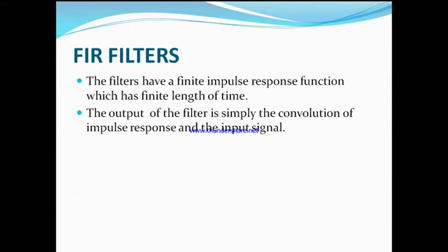Before that, we should know what is meant by FIR filters. These filters have a finite impulse response function, which means it has a finite length of time. The output of the filter is simply the convolution of the impulse response and the input signal.